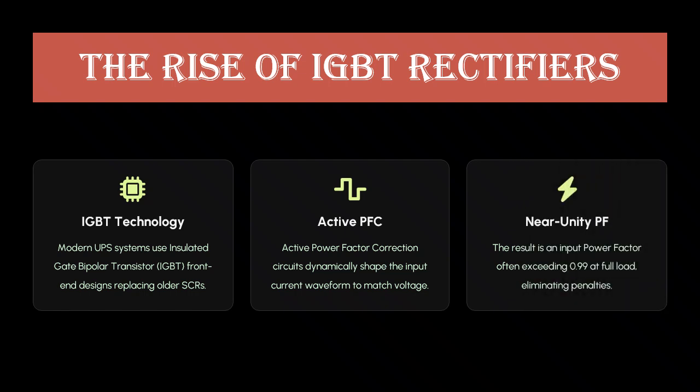The result is a substantial improvement. Modern UPS input power factors often exceed 0.99 at full load, effectively eliminating utility penalties and dramatically reducing total harmonic distortion.